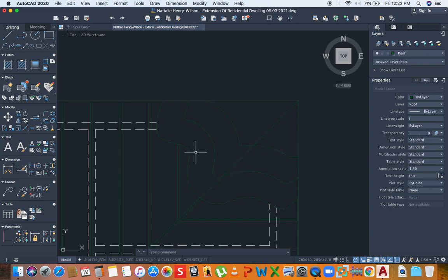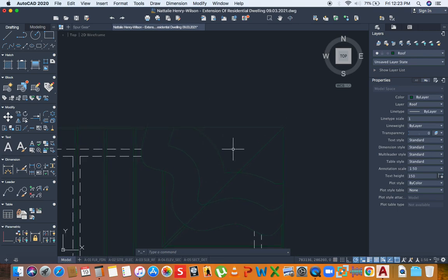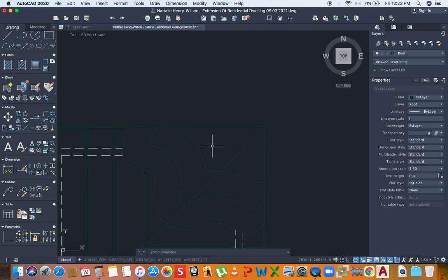So this is the plywood layer, and on the plywood you put something that you call felt. Now this is a waterproofing material, so this prevents water from seeping through the cracks and through the plywood into the building. And then after that plywood sarking layer, you would have your roof tile on top of that, and the roof tile adds beauty to the roof. It also does a job in allowing the water to run off properly.